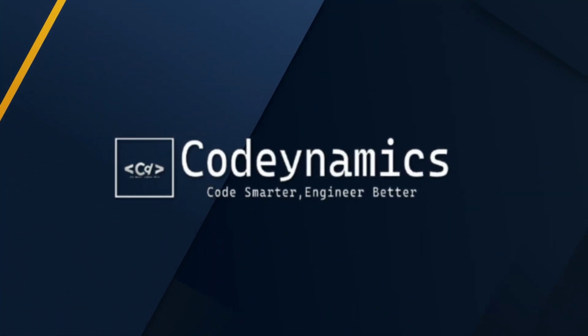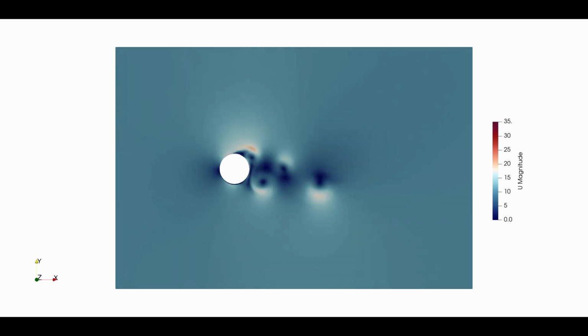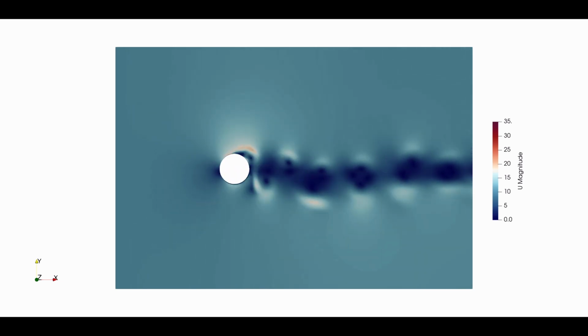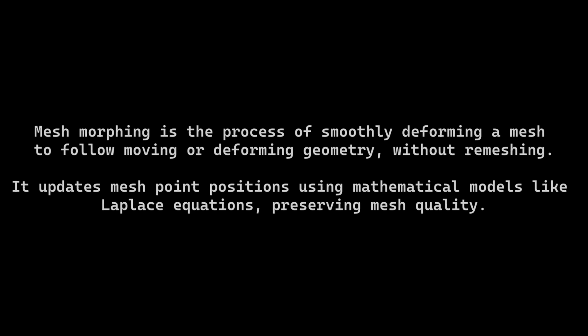In this video, we are simulating a 2D cylinder undergoing vertical oscillation using mesh morphing in OpenFOAM. So instead of using a rigid mesh or remeshing every time step, we will use OpenFOAM's dynamic mesh capabilities to smoothly deform the mesh around the moving cylinder. So this is what we call mesh morphing.